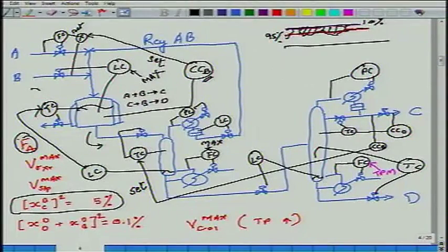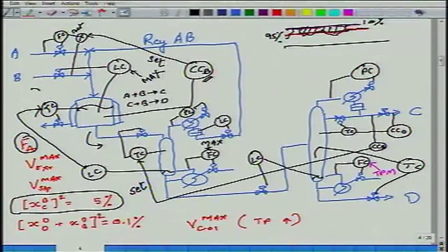If the FA is too much, reduce the steam set point. If the FA is too little, jack it up, right. I can always adjust it to get whatever FA I want, yes or no? Okay. V reactor max, well, that is coming from the set point here. This set point is kept at max. Second thing, V stripper max, well, it is already at max.